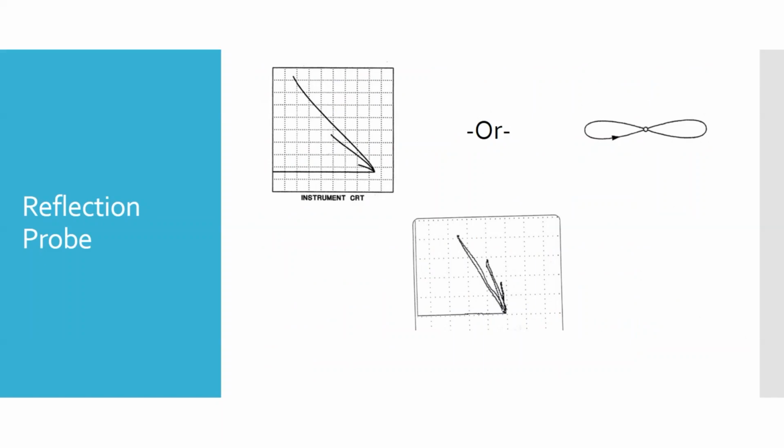What you're also seeing on here, remember I said there's an indication where the probe was set on the part or it was removed? That's called liftoff. That's this line across the bottom that's going off the side of the screen. And that's a major one, right? You're going to get the biggest change in inductive reactance when you put the coil on the part or take it away, right? That's the biggest change in the amount of metal in front of the coil.